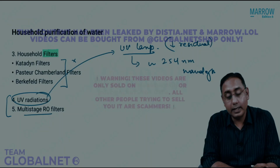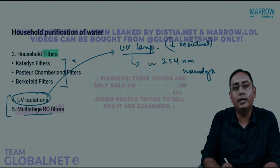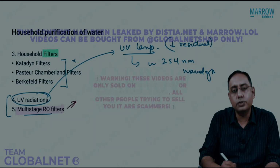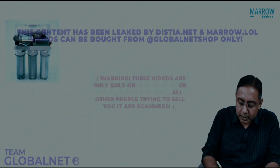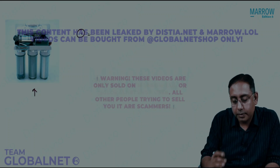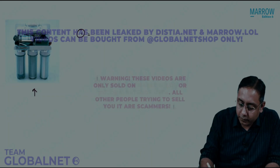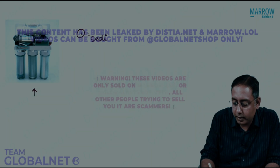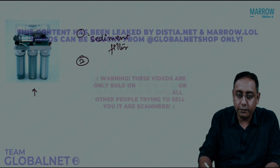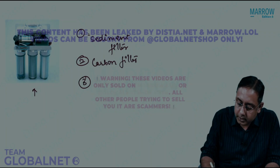The problem is there is less residual effect, and what is most commonly used in your and my home is the RO filters. So in RO filters, how many types of filters do we have in the RO system? In the RO filters, there could be different stages, different chambers. The first chamber is a sediment filter. After the sediment filter, we have a carbon filter. Third is a GAC filter.